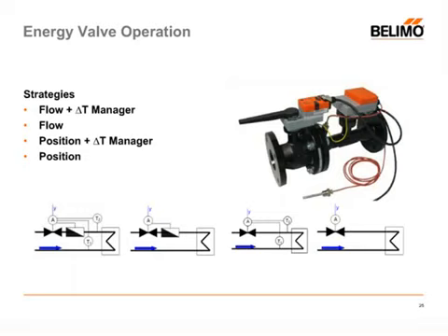And then from there, they'll turn on the delta T manager. So now, taking all the benefits of going from pressure dependent mode to pressure independent mode, I'll go one step further with incorporating the delta T manager, measuring that delta T across the coil and optimizing the coil based on the current coil condition. We talked about the things earlier in the presentation taking effect on the coil. This is what we feel is the optimized strategy to get the best power output for the coil's condition.